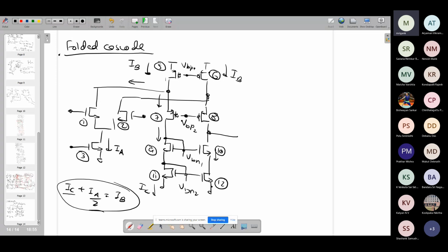So when you are sizing this transistor or establishing the mirroring current, this is the ratio we need to be aware of. This is the current division taking place. The top source constituted of M5 and M6 is providing current, like a current source, to both these branches, and M3, of course, determines how much current will be consumed by the input branch. So it takes some fraction of IB. IB has to be significantly larger, maybe double or at least 1.5 times that of IA. That is clear.